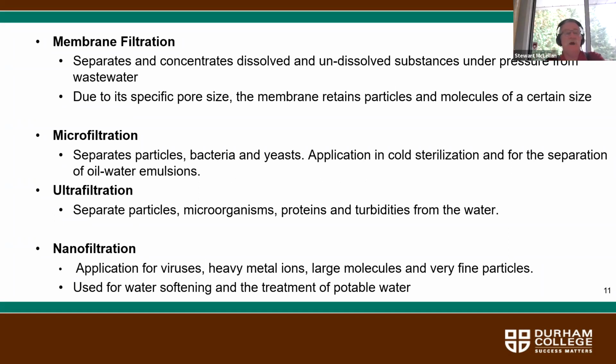Microfiltration separates particles, bacteria, and yeast. Application: cold sterilization and the separation of oil-water emulsions. I think I spoke briefly, I think it was in the last class, about emulsified oils and how emulsified oils can be very problematic because they are difficult to remove from wastewater, because they essentially become suspended in the column of the wastewater.